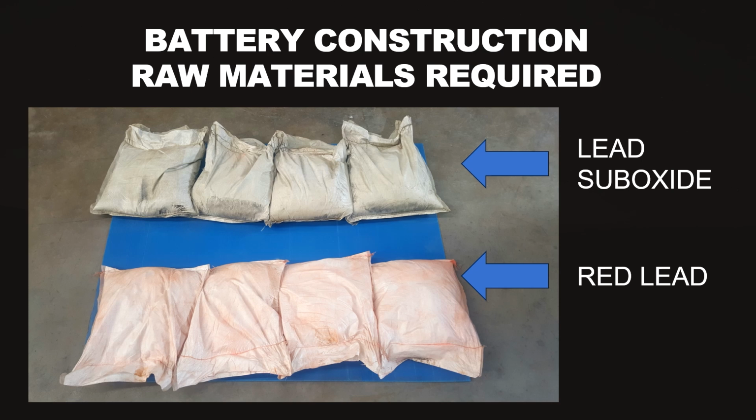Tubular plates are manufactured by filling the tubes with a powder, paste, or slurry. These are the three methods by which tubular plates are manufactured, and this is how an industrial tubular positive plate is made. I shall now show you how a pasted plate looks and how a positive tubular plate looks in my next slide.